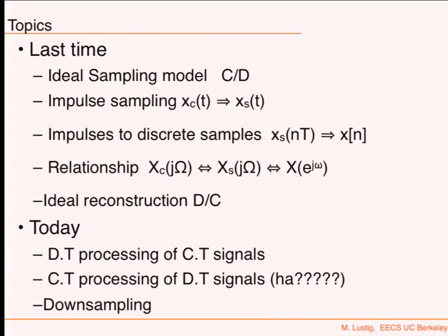We took a continuous time signal and then we constructed this impulsive signal that represents something that looks discrete, however, it is continuous, using impulse functions. Then we took those impulse functions and made them into discrete samples by just evaluating the function at equal number of samples. So we took the coefficients of those delta functions and evaluated them to get a discrete time signal.